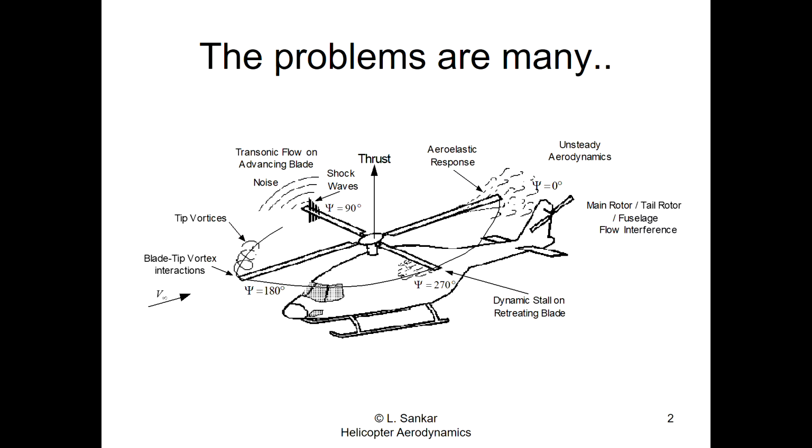The shocks shift the pressure distribution aft of the aerofoil. The shocks themselves move. They sit on the back end of the aerofoil, say around 40% or 50%. The elastic axis of the blade, where the structural loads are borne, is around 25% of the chord, the aerodynamic center for subsonic flow. So sometimes you get a large nose-down pitching moment, twisting the blades down.